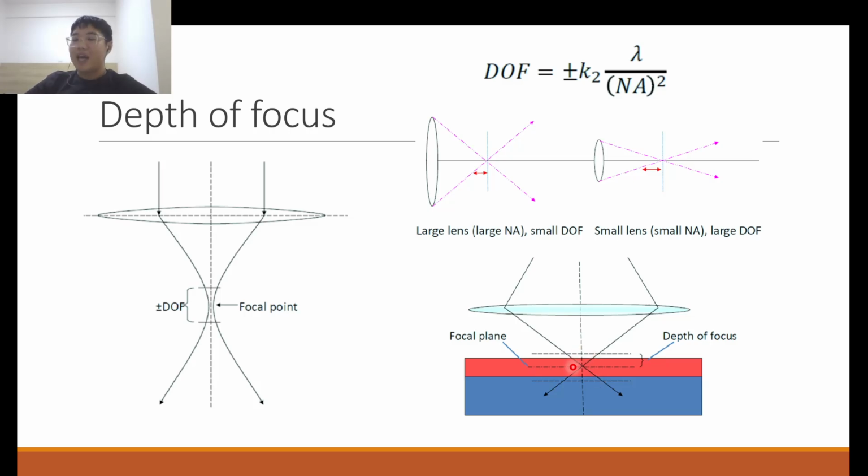And we cannot have too thin a photoresist, because remember, photoresist is used as a mask for later processes. It's used to define certain features for later processes. If your photoresist is too thin, your subsequent processes can erode away the photoresist and the patterns in it, resulting in a degradation of the precision of your subsequent process steps.